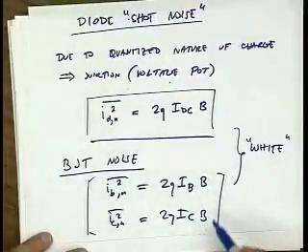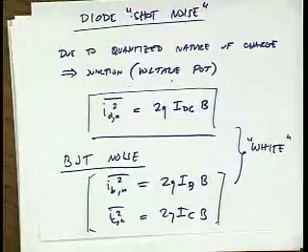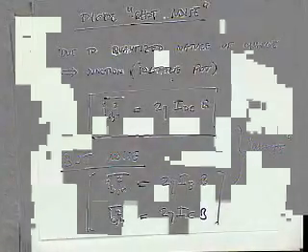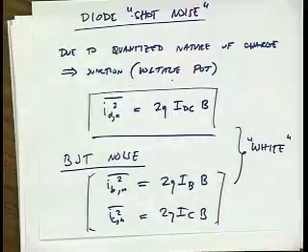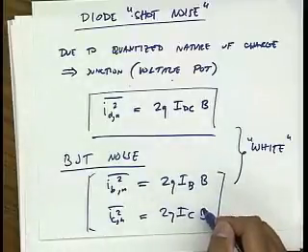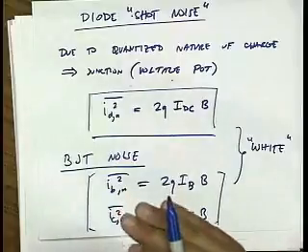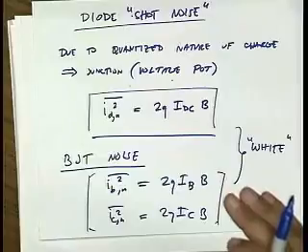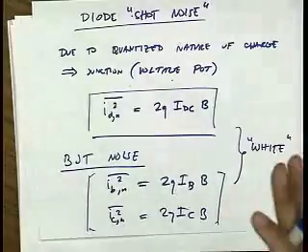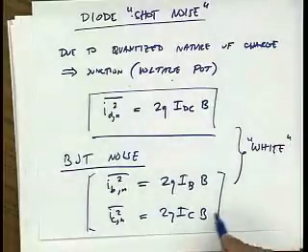Do you guys think these two noises are independent? Why? Yeah, it might bother you because you might say, well, the DC current is just beta times the base current, right? Collector current. But here we're talking about two different junctions that are being crossed, and there's a base in between them, right? So if a carrier crosses the base collector junction, it's going to be basically this noise source.